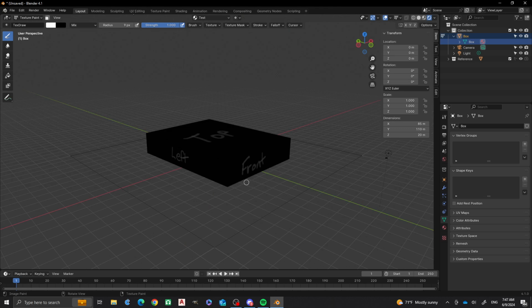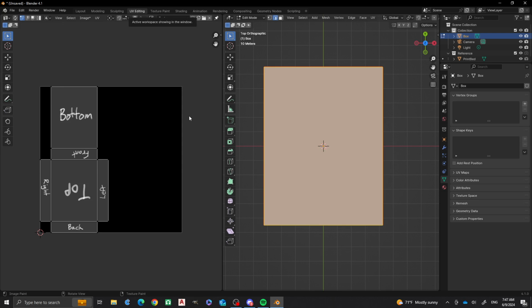Okay, now if I go back into my UV editing screen, you'll see how these are oriented. You notice that they're in a bunch of different directions. And because I did that, I press Z on here. These are oriented in the way that I had as I was doing the editing on the orthographic views, so I was able to get all these determined as to the orientation of where they need to go. So the top looks like it's upside down on this image, right? Bottom looks like it's right side up.